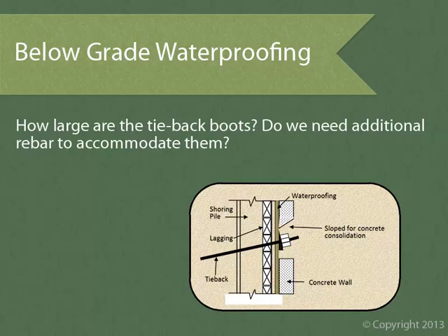Temporary shoring is a means and methods of construction, so tiebacks won't be shown on the contract drawings. Many cities and private owners require that tiebacks be detensioned after the building construction has reached the point that the shoring is no longer necessary. This is because tension strands below grade pose a snapping hazard to future digging.